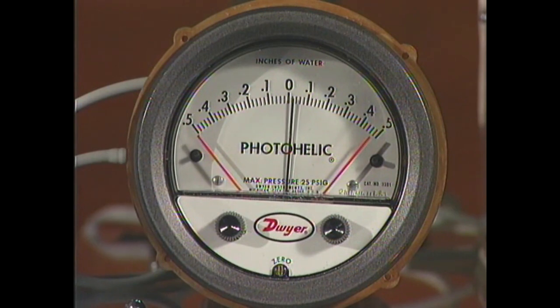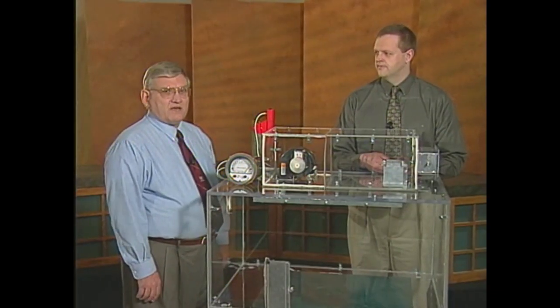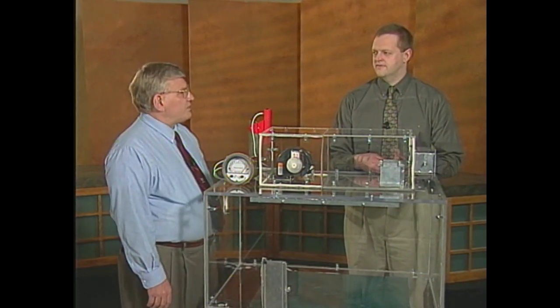Now, if we increase the amount of outside air going into the space, in other words, the ventilation air, you notice the static pressure start to rise in the building, 1/10 of an inch. But if you go to full economizer, the static pressure really jumps in the building, in this case as high as 0.5 inches positive. John, how do these pressure changes occur through the 4 system operating modes?